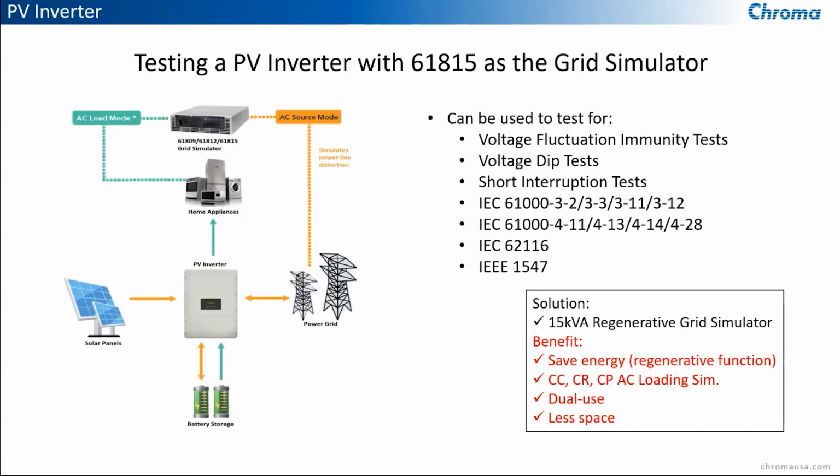So with the IEC 61000, that standard limits and measures the methods for low frequency emissions on the AC mains, while the 61000-4 sets limits on the susceptibility or immunity of the equipment powered from AC mains.